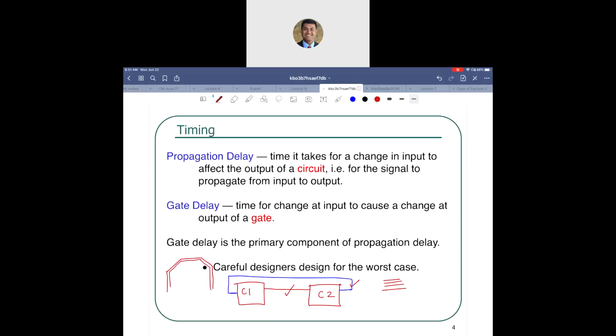Depending on the speed of the signal, there will be limitations on the angle at which the wires can bend. And of course, we have been talking about the lengths. We have to make those lengths consistent and so on. So the digital designer, Charles says, is that why? Yes, it is. That's why we have all those squiggly traces.